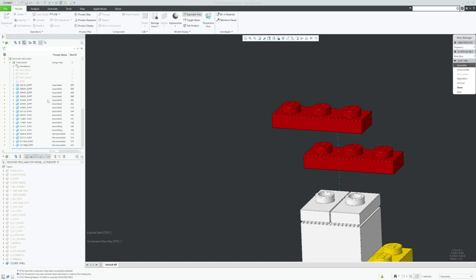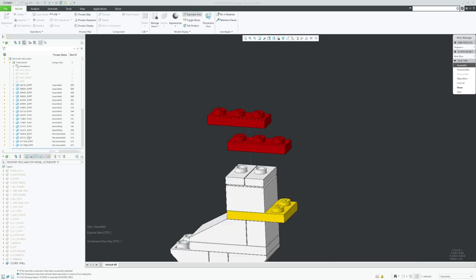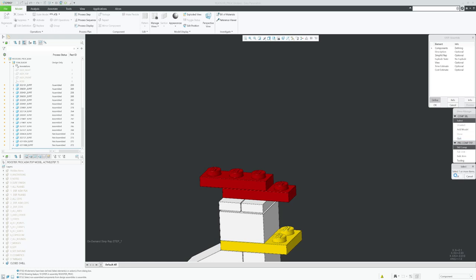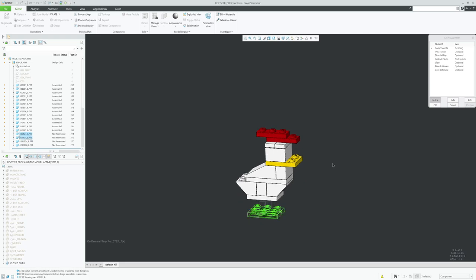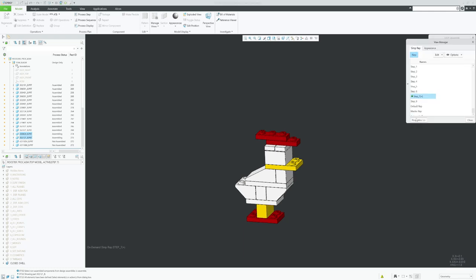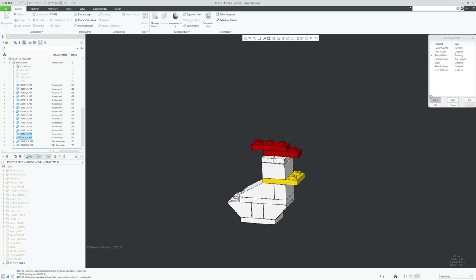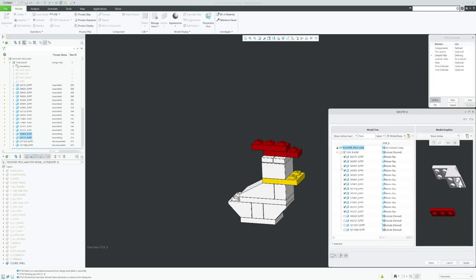Next step, assemble. Let's add this one and this one. Click OK. No, they haven't been selected. Quit. Components, define. I will select 1, 2. OK. Done. Simplify representation, define. Double click on underscore 8. Edit definition. Activate the next two components.